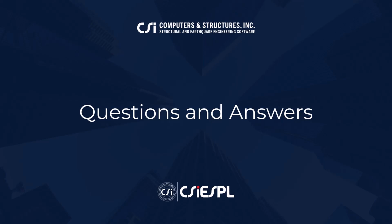That is a question about modes. The modes should be in X, Y, and torsion, or it can be Y, X, torsion. The first two can be anything, X, Y or Y, X. It doesn't matter. Torsion should be in the third.